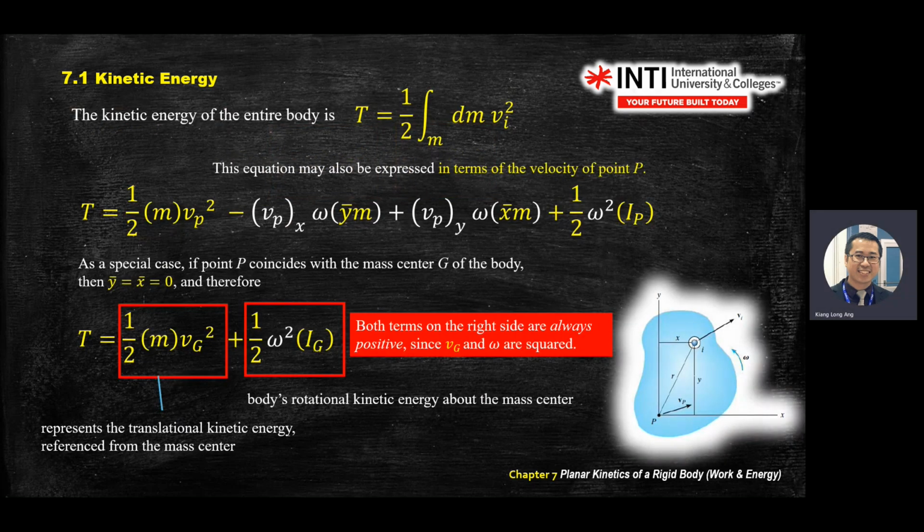So this is how kinetic energy works. If you look at the rigid body again, initially you have 3 components. So at least you should understand the background theory a bit. When you calculate kinetic energy for a rigid body, you have 3 effects. First, the mass, which is normally what you calculate in your physics class, half mv squared. Second one is the center of gravity.